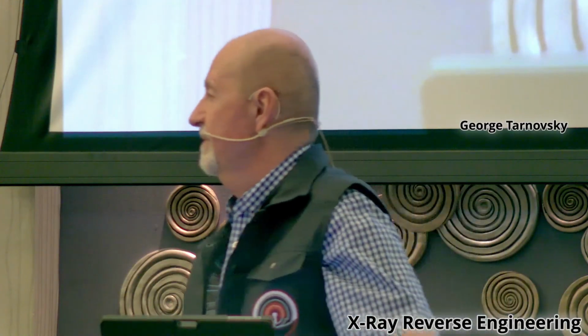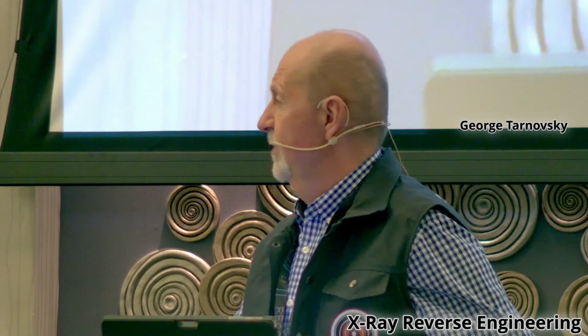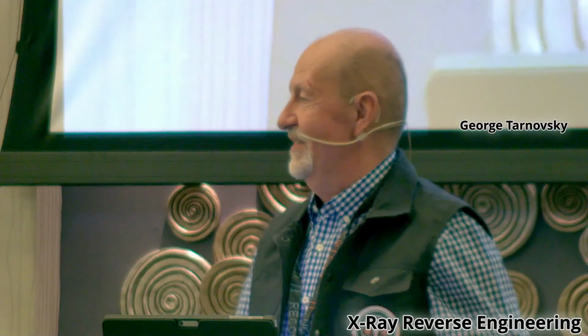Any other questions? Yes, we have one over there. I saw failure analysis as one of the uses. Are there other contexts to do this work in? Sure. Well, just in general, verification of placement, like I mentioned BGAs. Has anybody worked with BGAs, placing them? You have. Okay. So you know the complexity. It's really easy to have the balls short out because there's too much paste, and there's no way to verify that, with the exception of using an X-ray or power it up and see what happens.